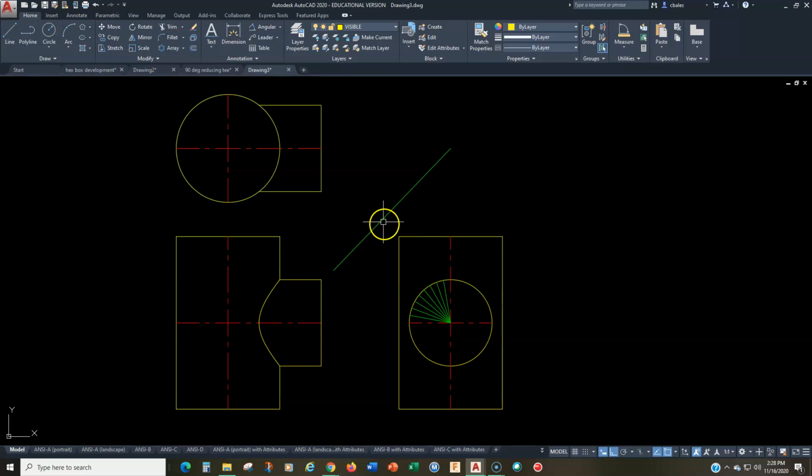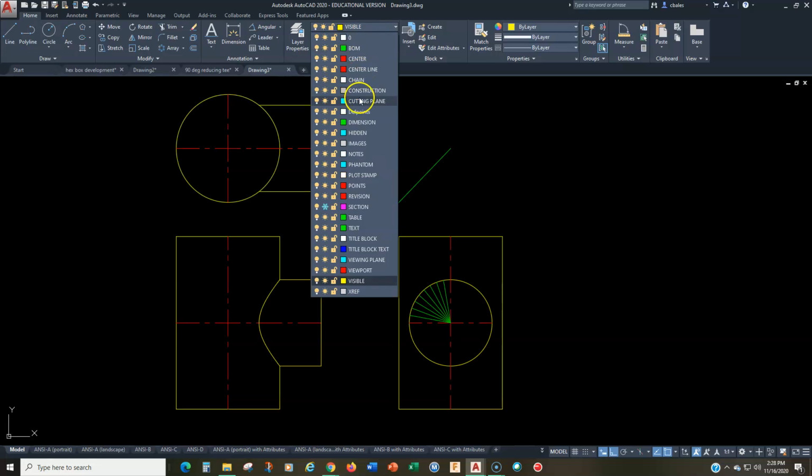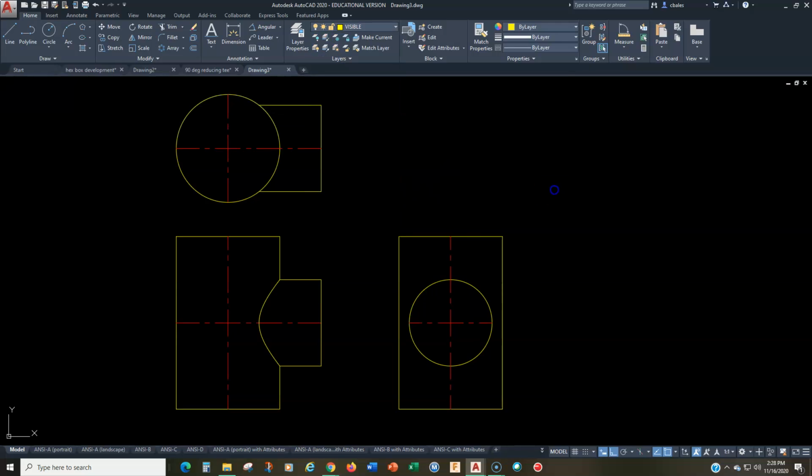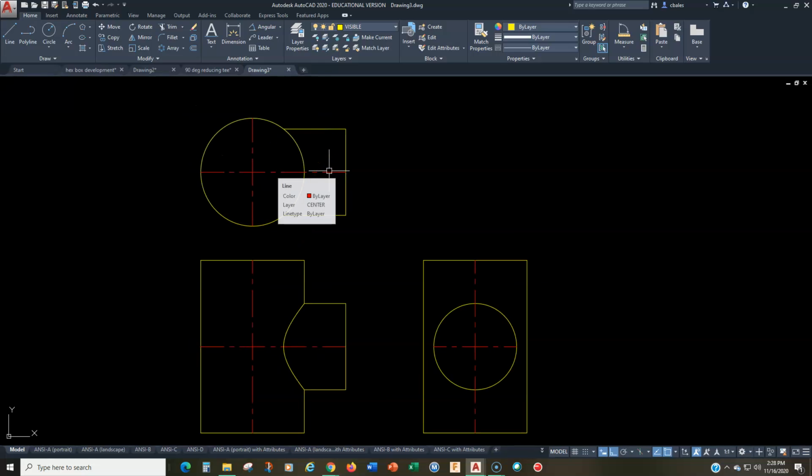Now, I'll pretty this up for you so you can see. I'll freeze that in case I need it later. So we can pretty this up. We need to extend these. So I'm going to use the lengthen command, delta 0.09, and we'll project those out like that, right? Because they need to be extended 0.09. You lose points if you don't have those like that.